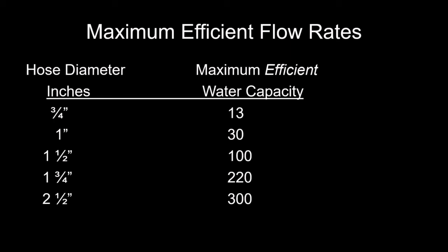I've done it. I've pumped 150. I've pumped almost 200 gallons a minute through a 1.5 inch hose, but it was through a 50-foot section during a pump test. It wasn't in a hose lay. So if I'm looking at any kind of significant distance, which is just a few hundred feet, these are the numbers that I'm kind of using.